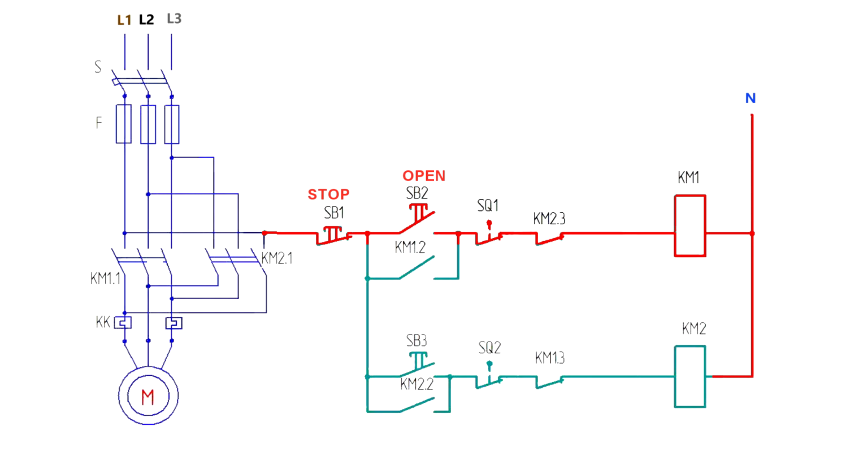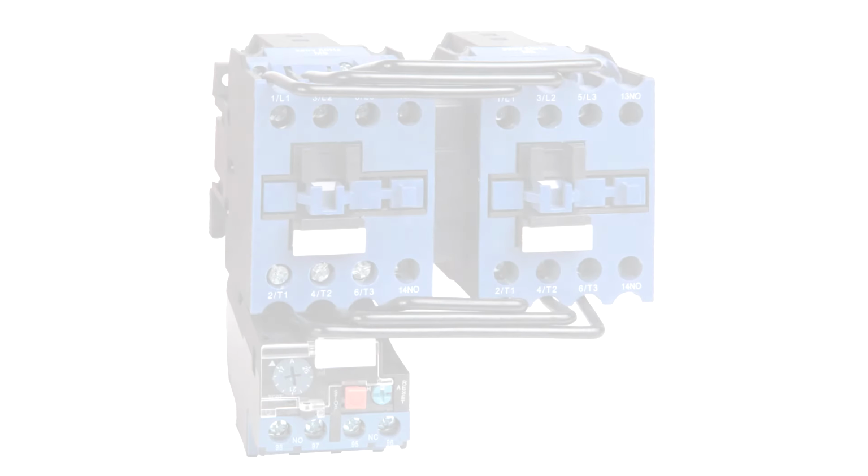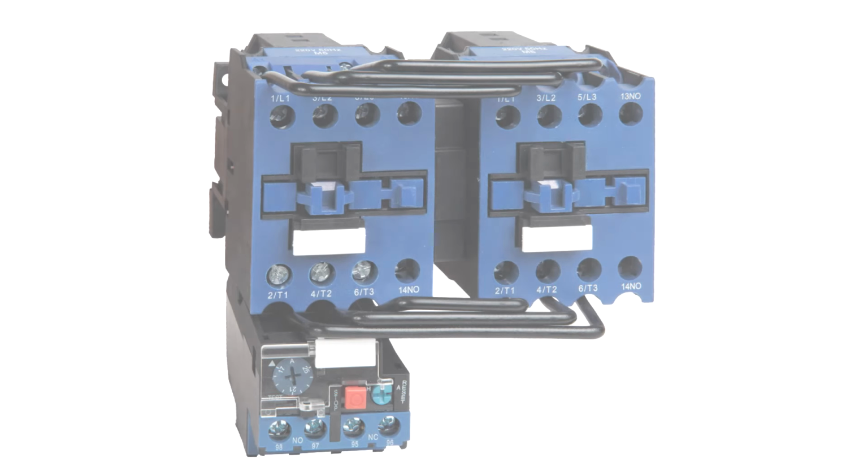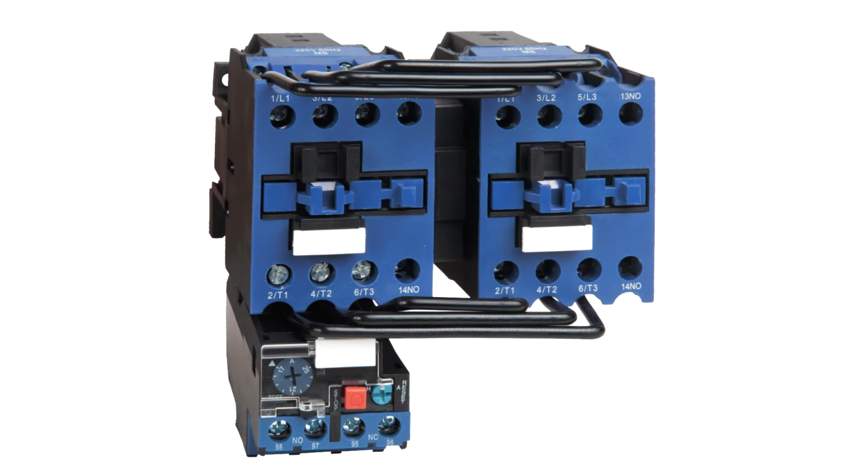Let's take a closer look at what a magnetic starter is, and what is the principle of its operation. I want to draw attention to one point. Very often a magnetic starter is called a contactor. In fact, this is not true. So what is the difference between a contactor and a magnetic starter? This question often perplexes the most experienced electricians, while many believe that the difference between them lies in their design, overall dimensions, or the value of the switched, rated, current, but this is not the case.